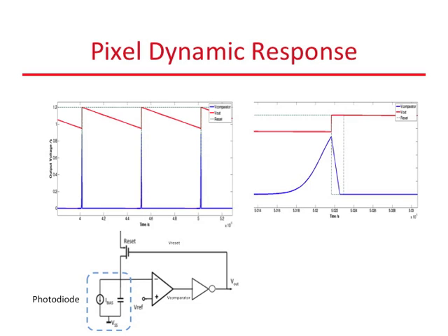This is the basic schematic of one pixel. Incident light is sensed using a reverse bias CMOS photodiode. The photodiode can be modeled as a current source representing charge generation from the incident light and a parasitic capacitor, corresponding to the diode junction capacitance, in parallel with the current source. The capacitor is initially charged to the supply voltage VDD, and the reset transistor is open-circuited. Incident light causes the capacitor to discharge, and subsequently the capacitor voltage decreases. As soon as the capacitor voltage crosses a threshold VREF, the comparator block switches low.